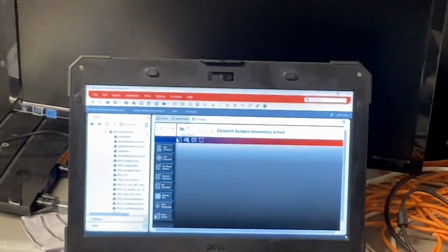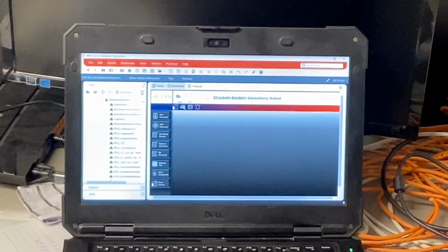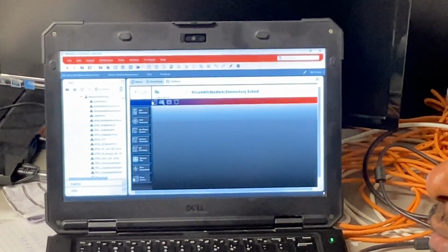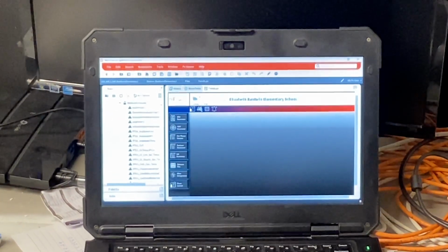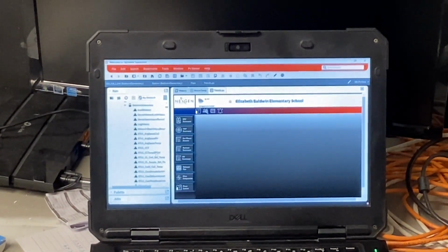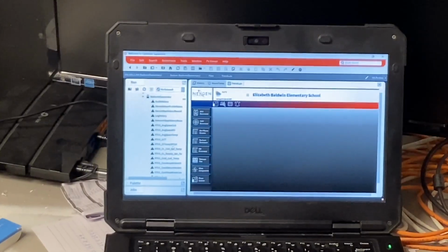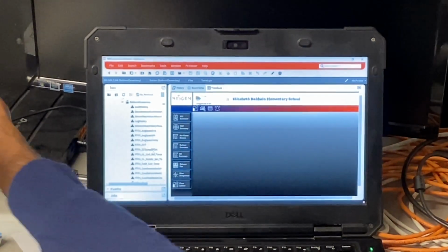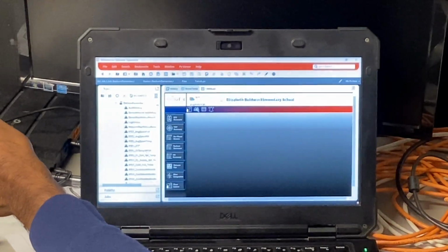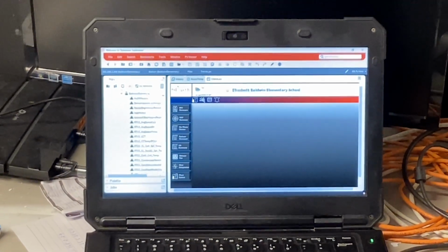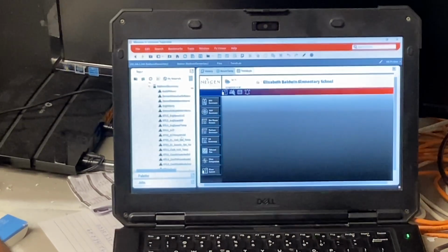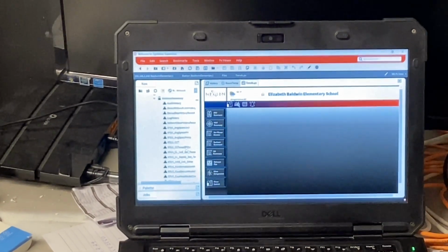Exhaust fan again is all based on occupancy. Do we have a separate RTU for the cafeteria? Yes, the MakeUpAir. When the kitchen hood is on, that gives a signal to turn the MakeUpAir unit on, and based on the output from the kitchen hood controller, it drives the fan speed as well.